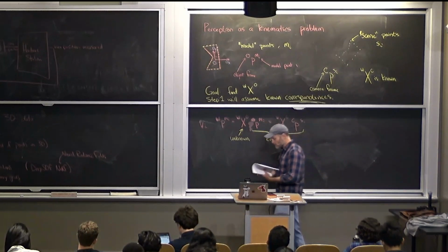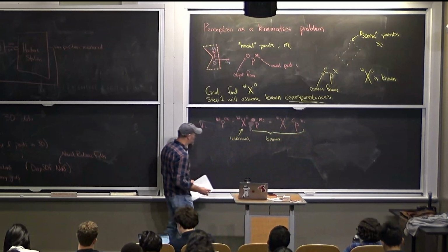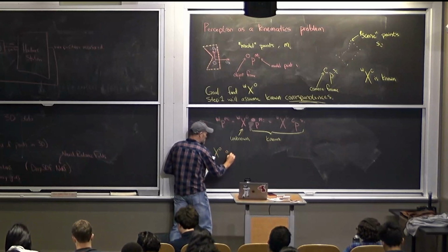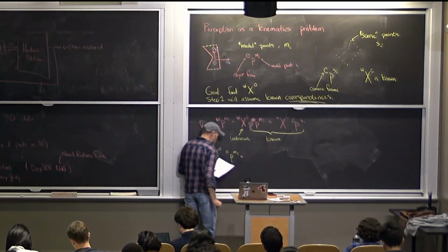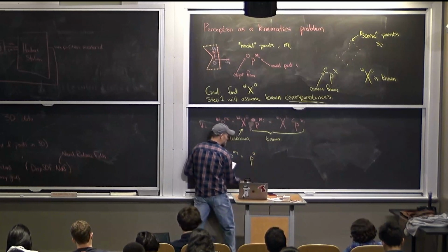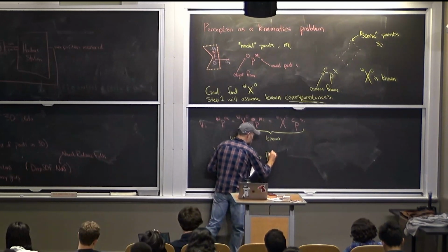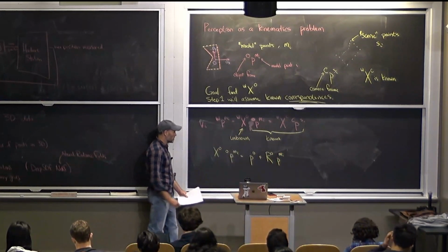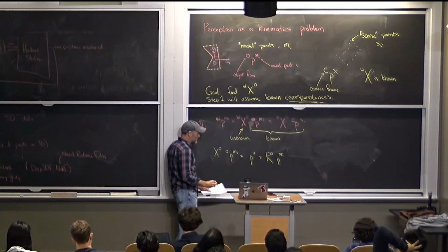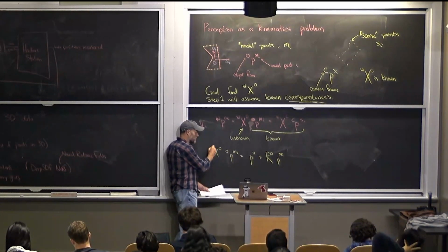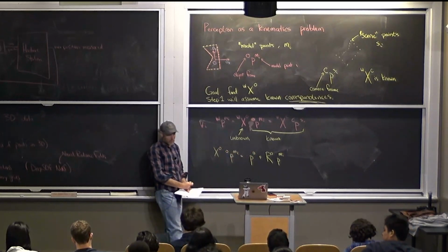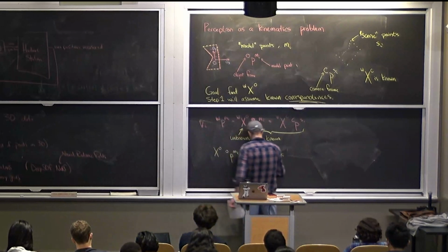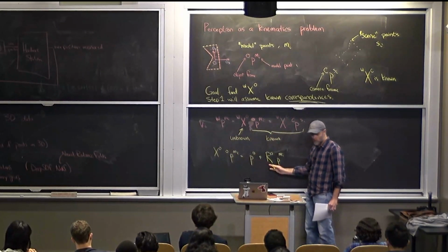Now, if we dig in just a little bit to the pose representation, you remember from our spatial transforms that doing this is equivalent to both the translation plus the rotation. I'm leaving off the W for my shorthand, but the W is everywhere. So really, the unknowns are both the translation and the rotation.